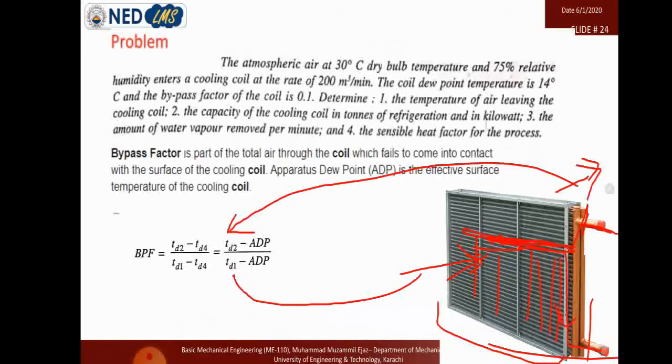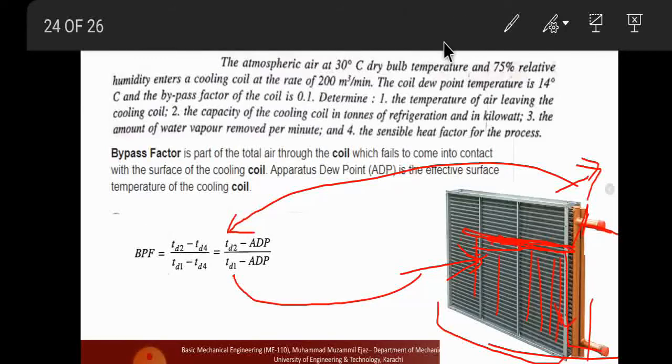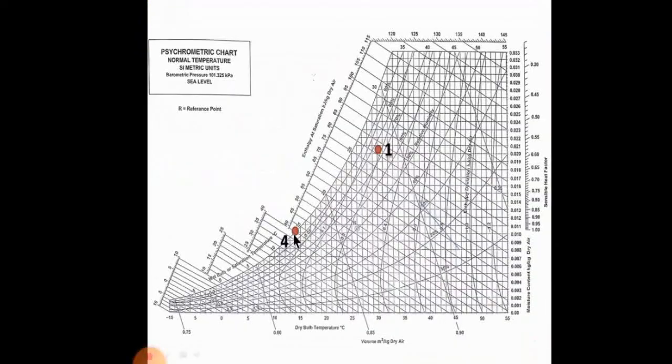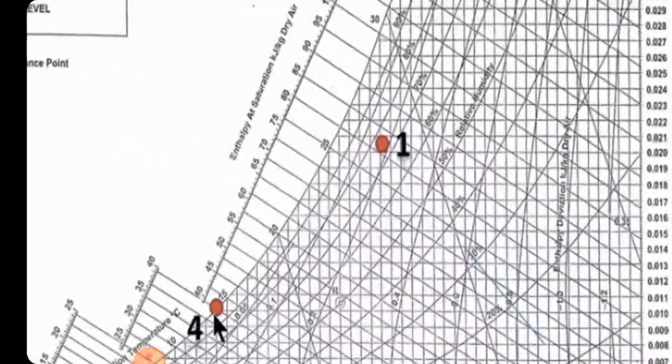As per the condition, we need two pieces of information: one is dry bulb temperature, and the other is relative humidity, or if the relative humidity is not available and they give the wet bulb temperature, then we can still come to our current position.